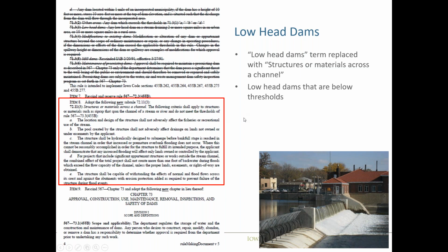And that is in the miscellaneous obstruction or floodplain section for the thresholds. Typically, the larger river dams will be classified as a dam. It would take about, just an estimated size, a 12-foot tall low-head dam on a river, 80-foot wide, with a stream slope of 0.25%, would meet the new thresholds that we'll talk about in a little bit.